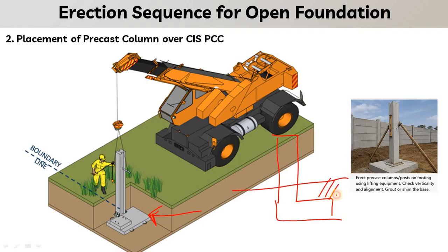So this kind of element is a single element which is feasible for precast, to avoid a number of joints, because if the number of joints is more, the element erection time will be more, and a joint is always a joint. So if we make it as a single unit, then erection will be faster, and the speed of work will be more.